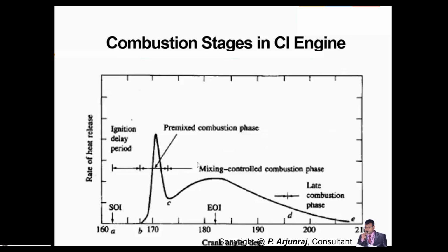This stage is called the premixed combustion stage, where the air and fuel get premixed. It's not going to be completely mixed. Then the pressure comes down, and again when the air and fuel get mixed again, you get high pressure and high heat release.